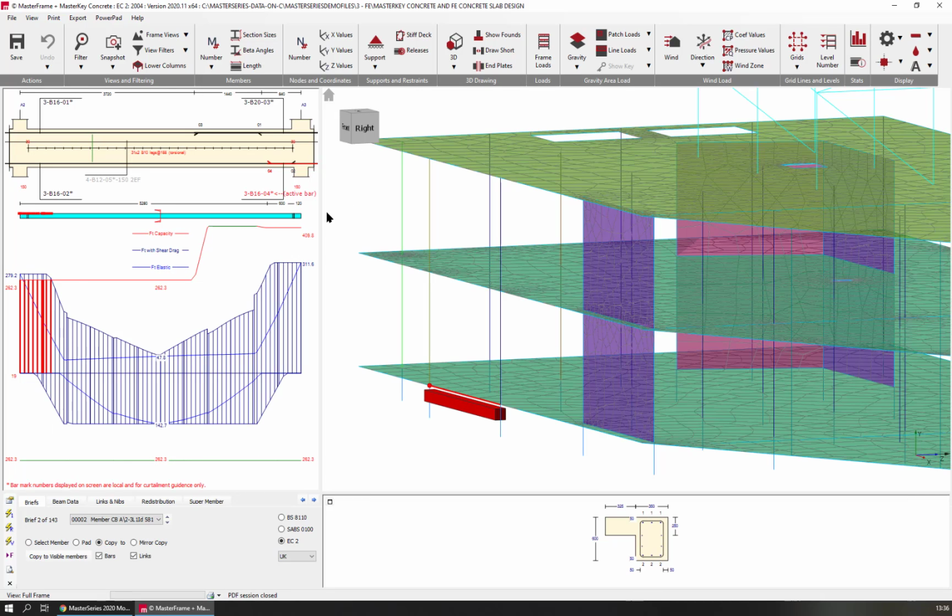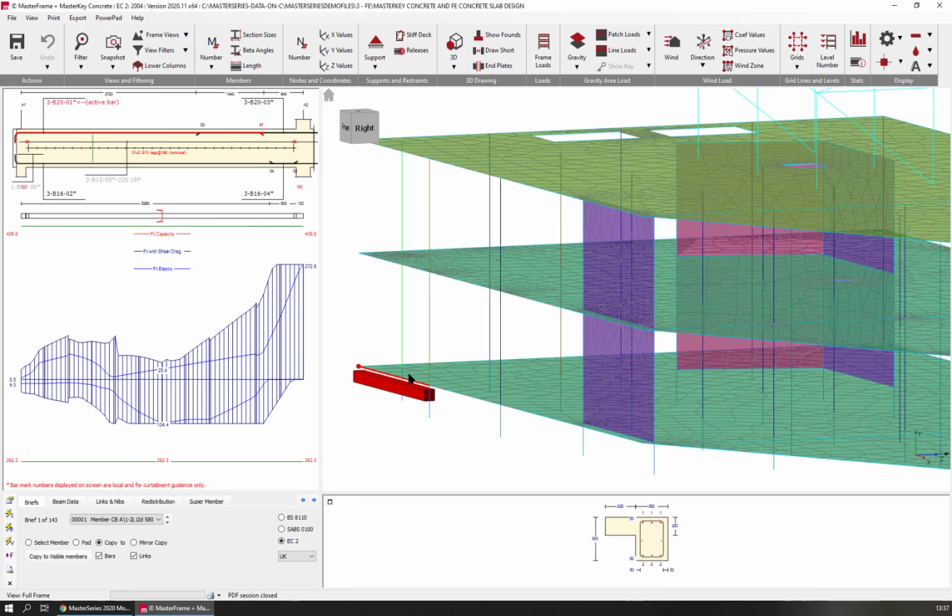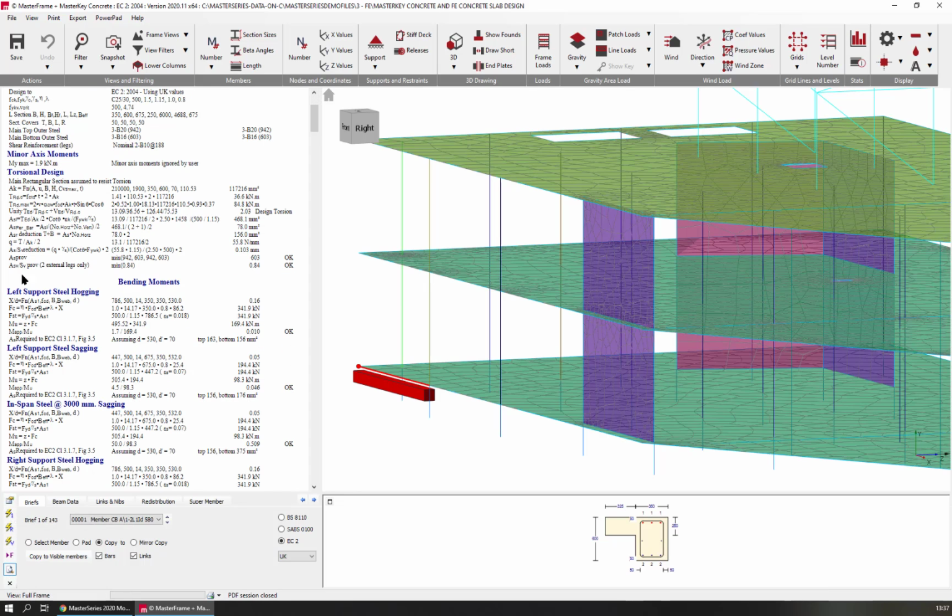And we'll see it gets a bit annoyed because you'd really need to keep the 20s on both sides. And there we go. That now works. So 16s in the bottom, 20s in the top, and we are good to go. And that is a reasonable approach. You will notice, even though we're shallow on these beams, that they do have side reinforcement. The side reinforcement is because when we look at our results, there is a degree of torsion from the slab automatically coming through.